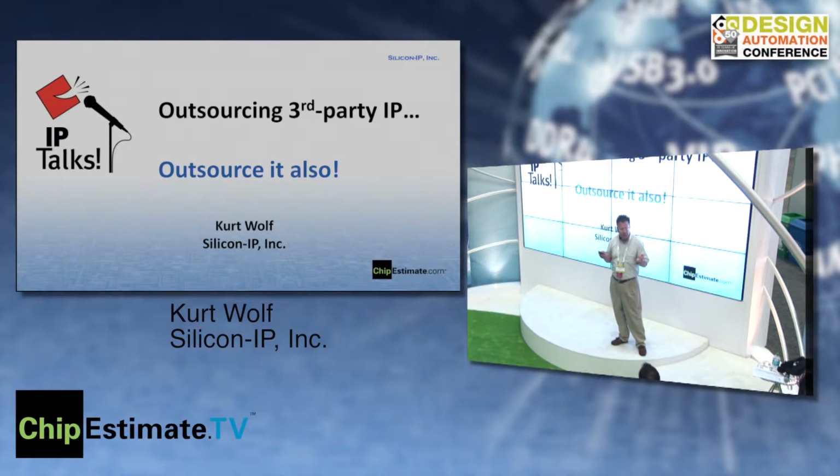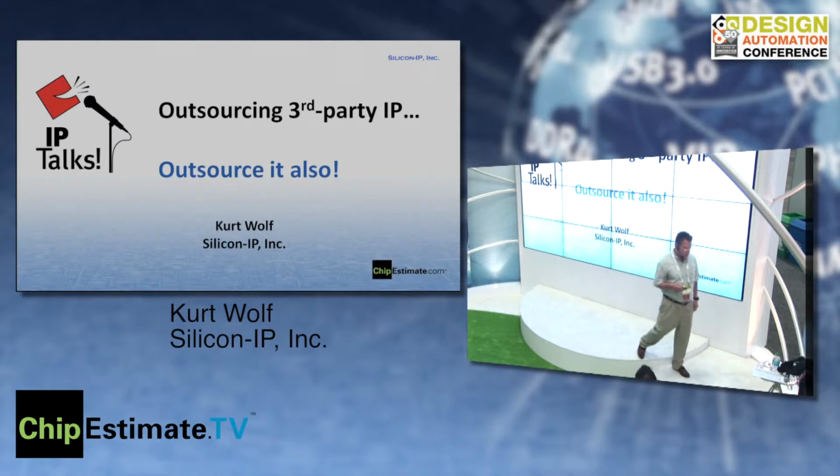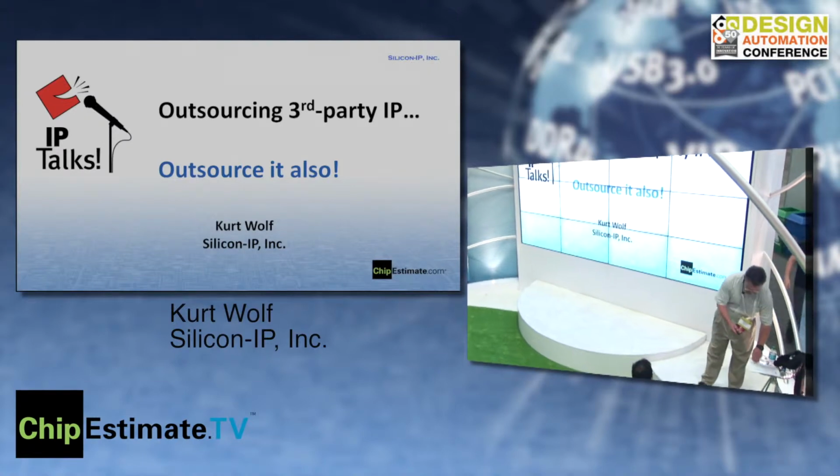So you want the IP that is going to be most compatible with your system in terms of SPICE models, design rules, and testing. We focus primarily on the silicon-based IP, sometimes referred to as GDS IP or hard IP. The RTL components we get involved with are when there are controllers involved, but we are primarily focused on what we call the GDS-based IP.